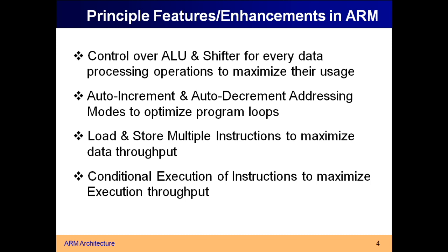So if you want to do it in normal C or assembly, what you will do? You need to initialize a pointer. You need to increment or decrement the pointer manually using the program. But here there is a dedicated incrementer block which can perform this auto incrementing and auto decrementing automatically. The decrementing and incrementing will be done automatically. Once the addition is completed, incrementing will be done automatically. You don't need to manually increment.